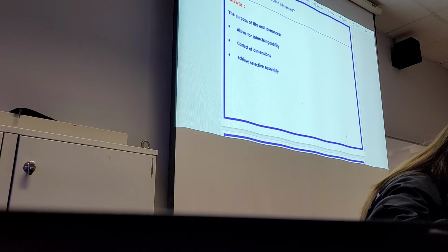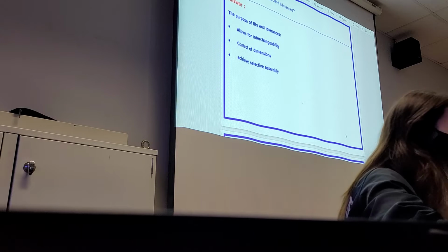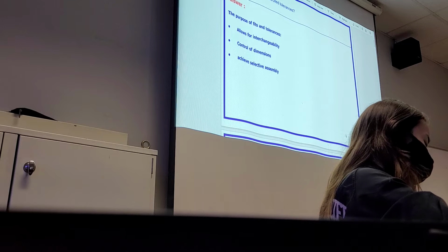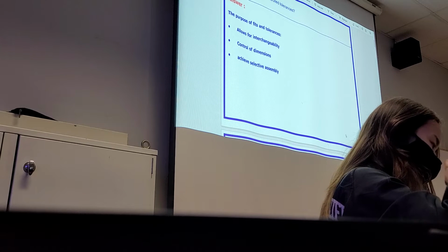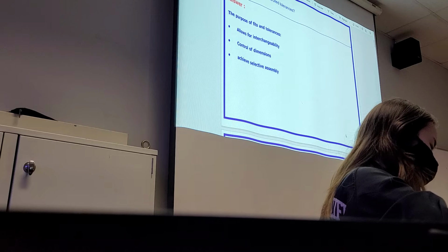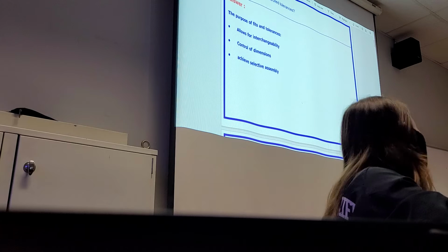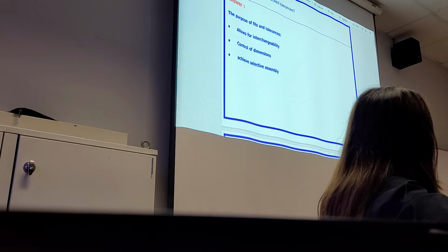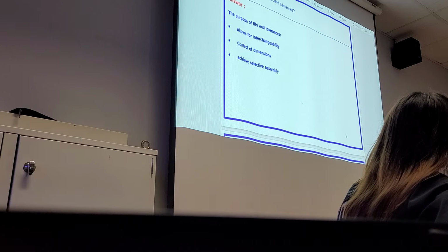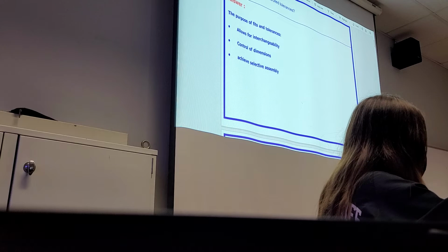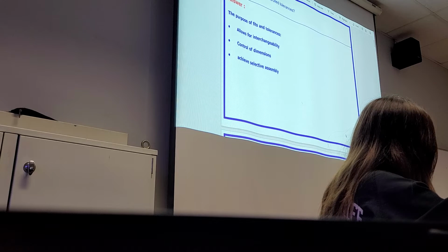Okay, so the purpose of a control dimension, the control tolerance, is to allow interchangeability. We can produce the parts from company A and company B. You can mix them up because they are all following the same tolerance. So whether it's produced by company A or B, it is interchangeable. You can buy a screw from another company, nicely fitting, because everybody follows a tolerance. The tolerance is basically a way to control the dimension, and we can achieve the assembly you want. You can have 3 conditions. Remember: clearance, transition, interference.